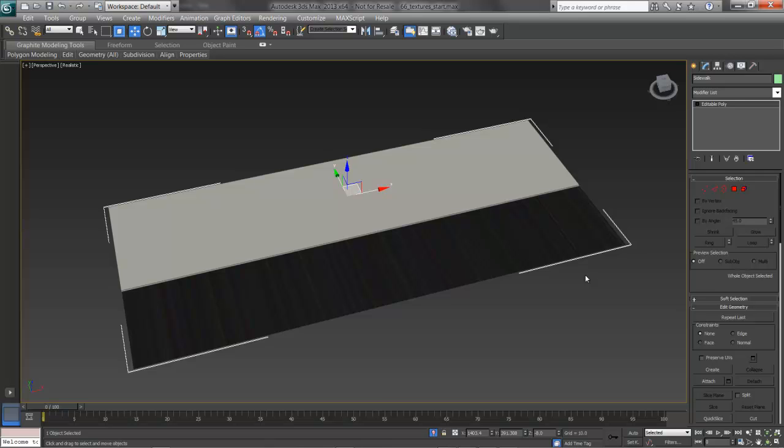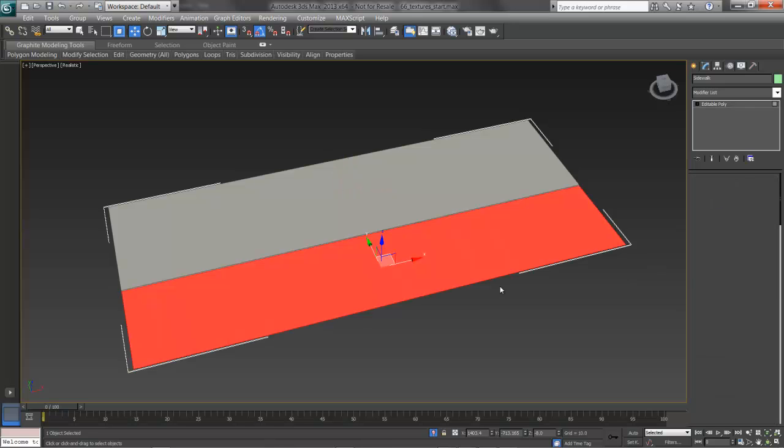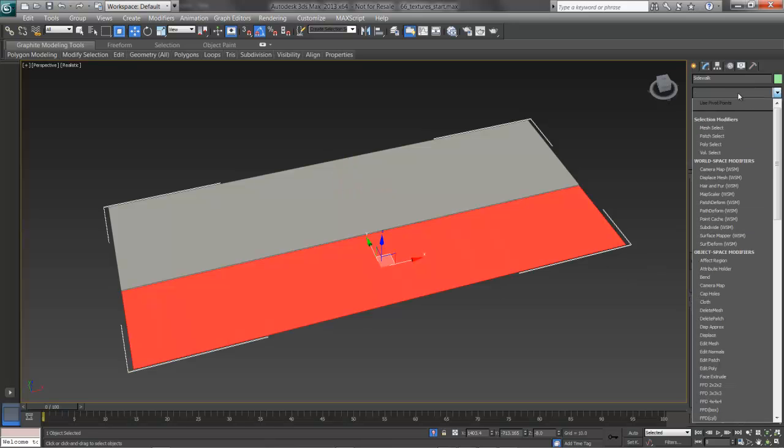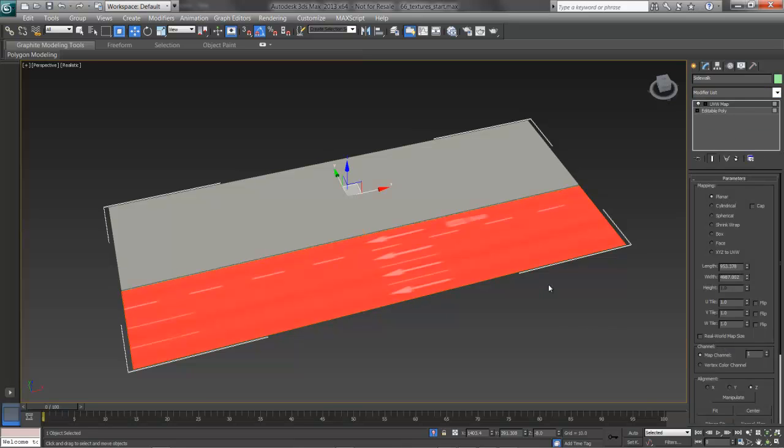Here's the other thing we need when we're starting to play with textures. Mapping. We need to tell this texture how big it should be and which way it should go. I'll make sure I've got that polygon selected, and under the modifier list, press U and put on a UVW map modifier. UVW for us refers to local texture coordinates on an object. And the reason they chose UVW is because XYZ and ABC and JKL were already taken. XYZ refers to object coordinates, and so to avoid confusion we needed 3 new letters. The mathematicians owned ABC, and the editors JKL, and so we use UVW.